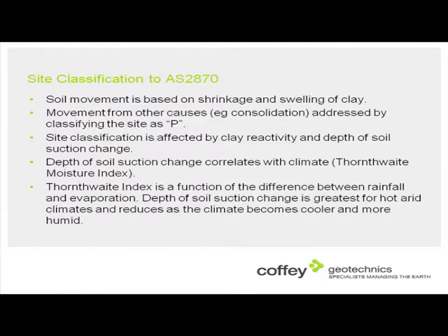Soil movements based on shrinkage and swell of the clay: well, the site classification that's used is based on that. If the movement's from other causes, say consolidation of a soft clay or a peat or something like that, then the site would be classified P.